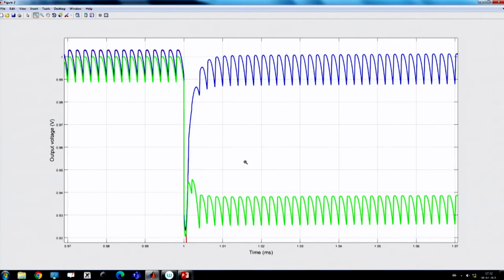consider one inductor and capacitor. So, we cannot avoid the output impedance of a DC-DC converter, but we check two things there. One is the DC equivalent, another is the AC output impedance. Because of AC output impedance, we are getting overshoot, undershoot here, but here we are intentionally increasing, emulating, not putting a physical resistance, by means of control by droop action.